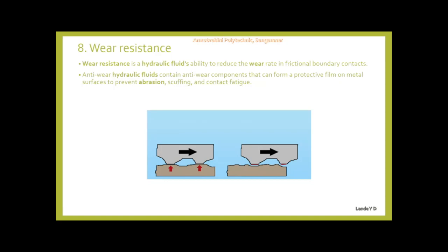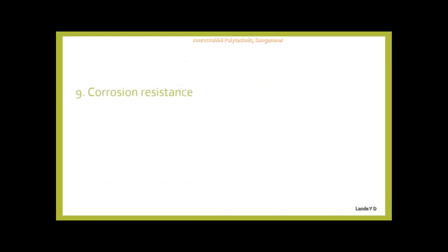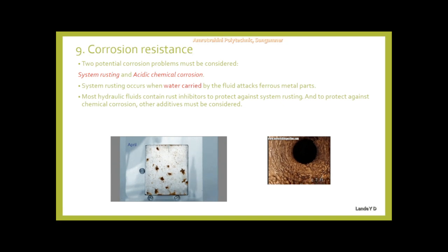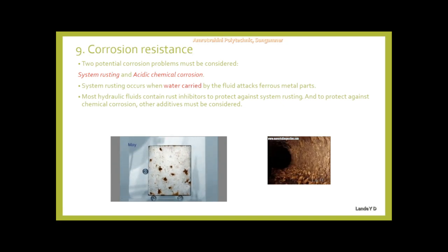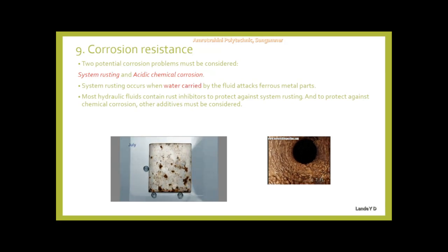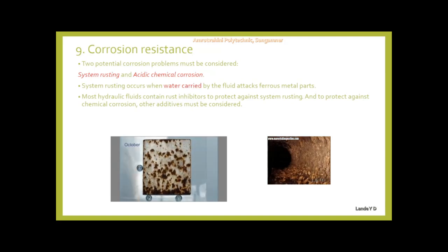Anti-wear hydraulic fluids contain anti-wear components that can form a protective film on metal surfaces to prevent abrasion, scuffing, and contact fatigue. 9. Corrosion resistance. Two potential corrosion problems must be considered. One is system rusting and second is acidic chemical corrosion.